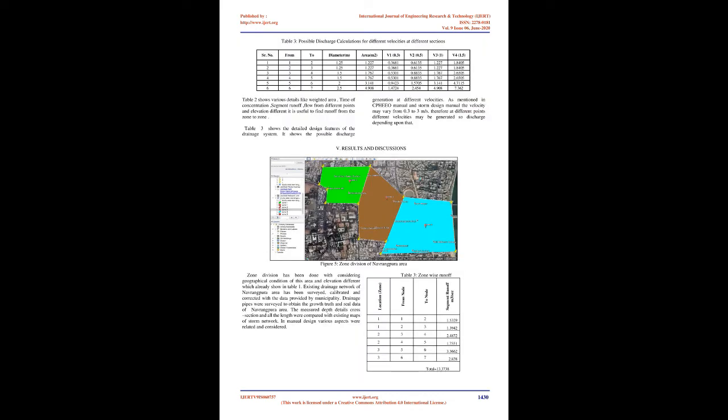4. Methodology. The field data required for the design of the sewerage system, such as details of existing water supply, the ward-wise population as per census, development plan, etc., were collected from the Navrangpura Municipal Council. In the present study, the rational method is used to estimate discharge for Navrangpura. Discharge is a major input for the storm water design, and also the geographical information of the city is essential to find out the general slope of the ground, which helps in finalizing the alignments and directions of the sewers.